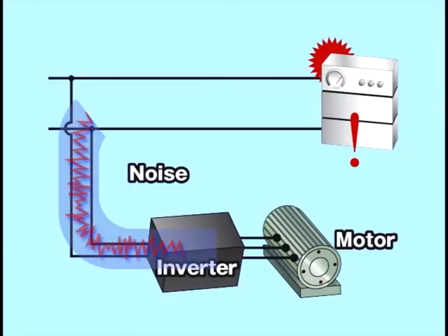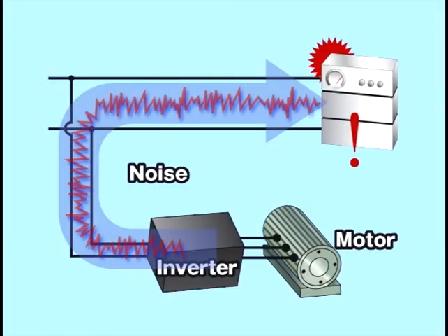Let us now take a look at causes, effects and countermeasures in connection with power converter-related problems. As with the chopper, power converters require power semiconductor switches, such as diodes and IGBTs. The power converter converts electric power by means of semiconductor switches. However, switching may generate high-frequency electromagnetic noise. This noise is known as electromagnetic interference, or EMI.